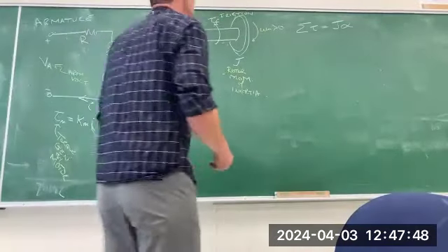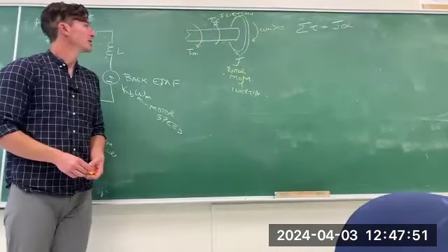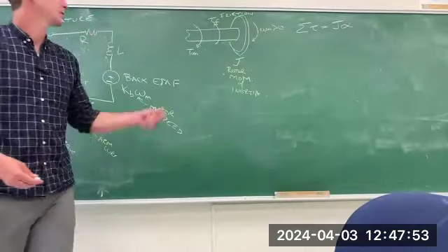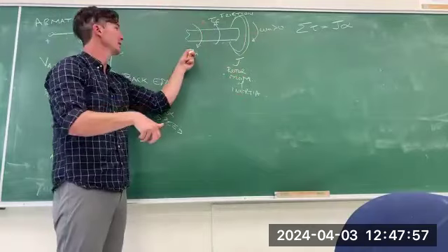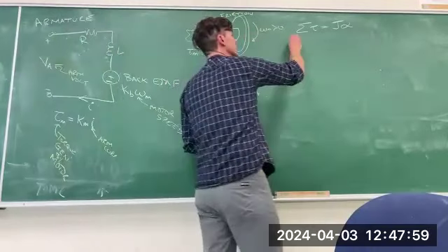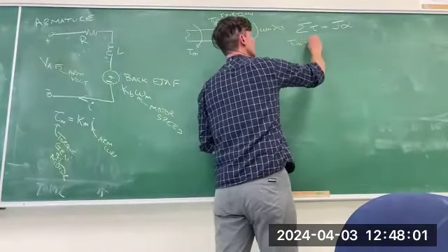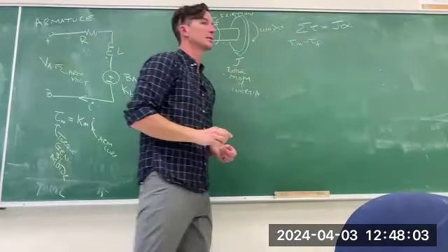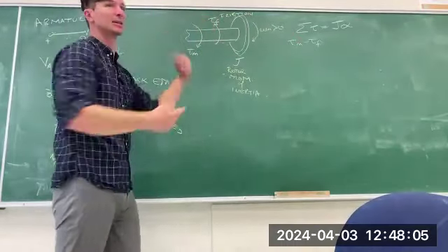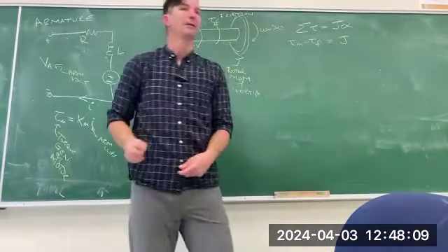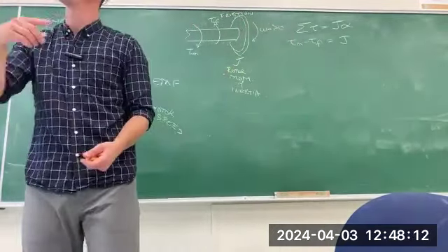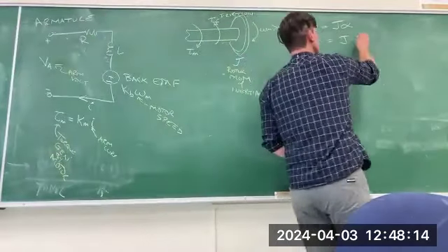So we need to decide what is a positive torque and what is a negative torque. Based on the fact that this omega m is drawn this way, and that matches this tau m, we should call tau m a positive torque and tau f a negative torque. They have to be different signs because they're acting in different directions. And rather than alpha, I think we should write omega prime, or derivative of omega.